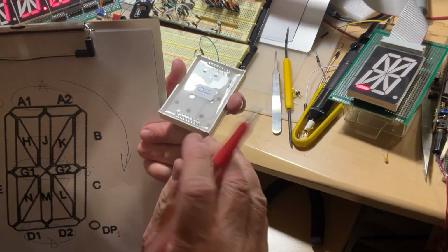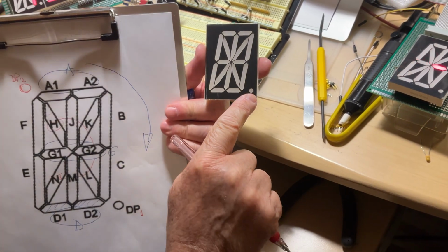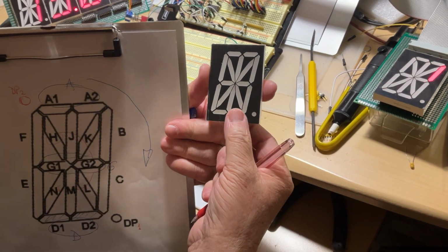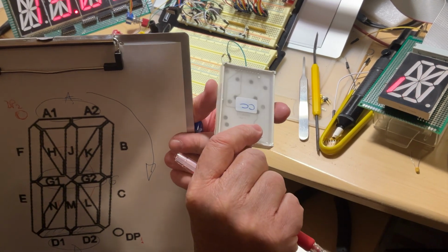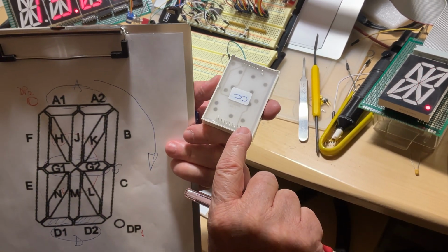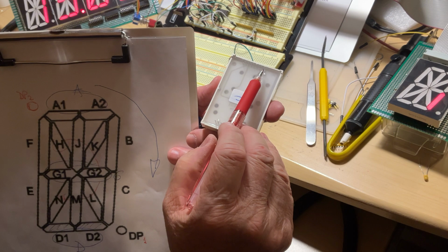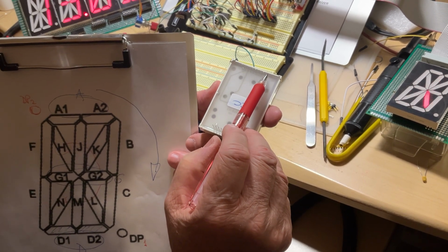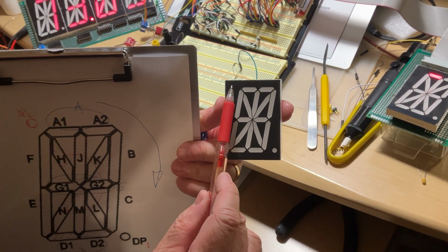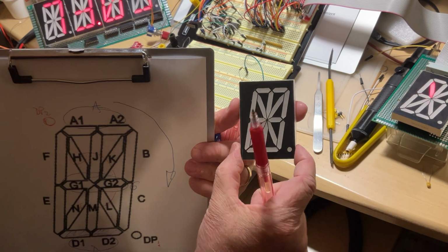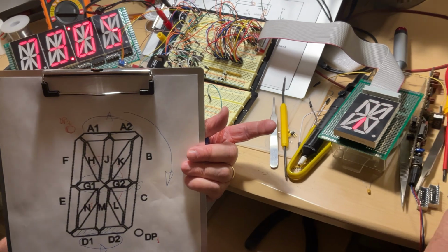The pins. If you take a look at the pins, you have to hold it with the decimal point, if there is only one decimal point, at the bottom right. And the pin number 1 is right here on my left. So when we turn it upside down, pin number 1 is going to come here. You count 1, 2, 3, and so on up to 10. And then 11, 12, 13, and so on up to 19. The pin 20 is missing. Why is this missing? Because pin 20 was reserved for the second decimal point here, which is missing on this one. So the standard package has 20 pins, but pin 20 is missing if the second decimal point is missing.